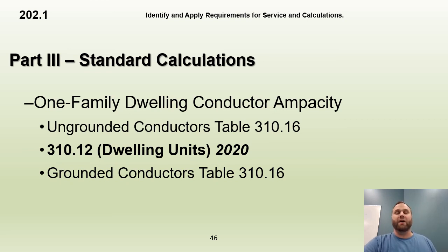Well, they don't make a 165 amp service breaker or main breaker. So now it is up to me as the electrician, understanding Article 240, 240.4 and 240.6, that I can size that up to the next standard size breaker, which I believe would be 175 amps according to table 240.6(A). That would be my next standard size breaker up.